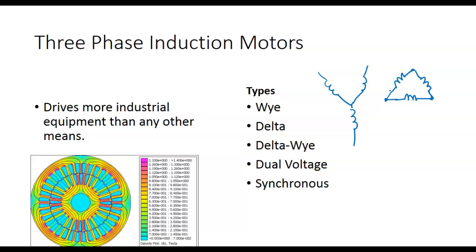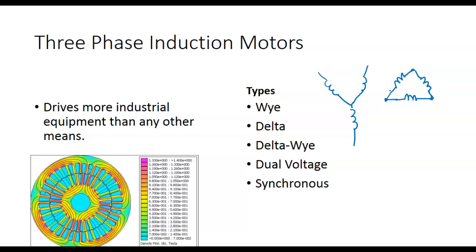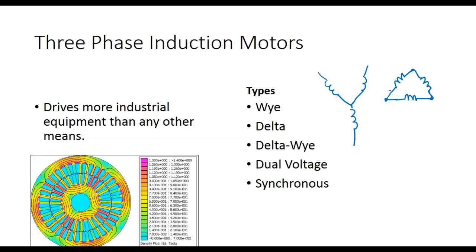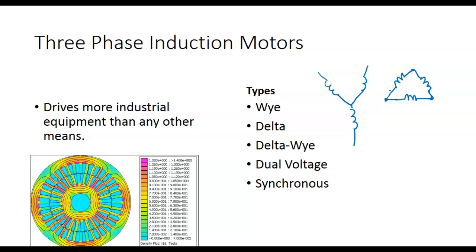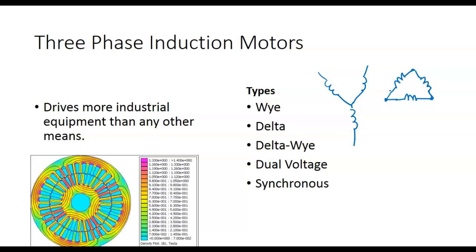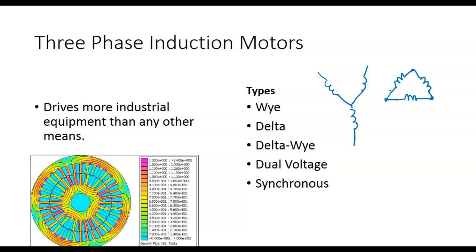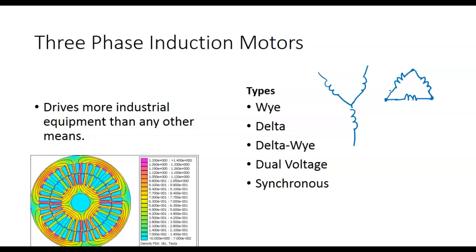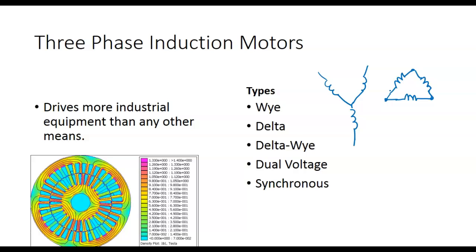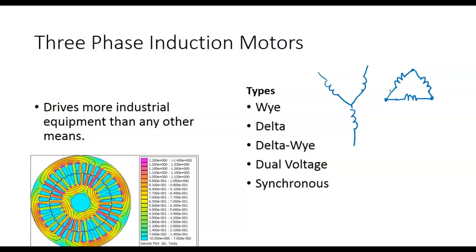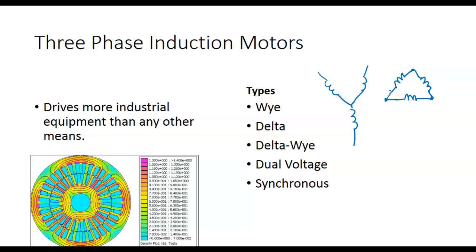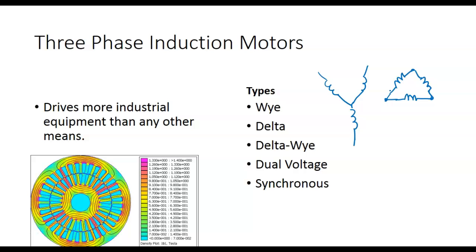Delta Y motors, we can start at Y, which makes it draw less current and produces less torque, and then we can switch to Delta. That's the only thing. When you get into motor controls, you're going to be dealing with what we call a dual voltage motor.